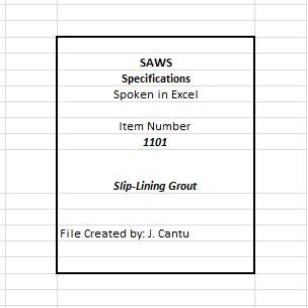1. Compressive strength: the grout shall have a minimum penetration resistance of 100 psi in 24 hours, when tested in accordance with ASTM C403/C403M-08, and a minimum compressive strength of 300 psi in 28 days when tested in accordance with ASTM C495/C495M-12 or C109/C109M-12.